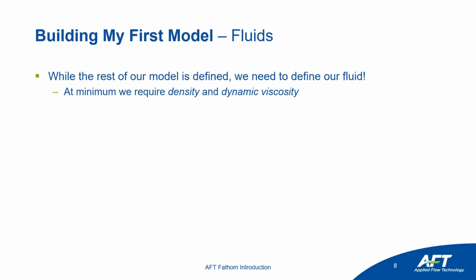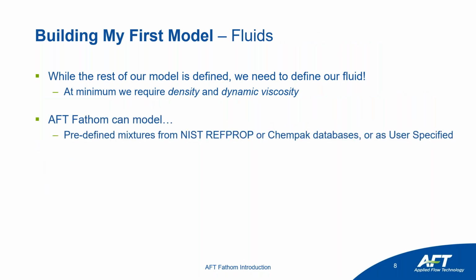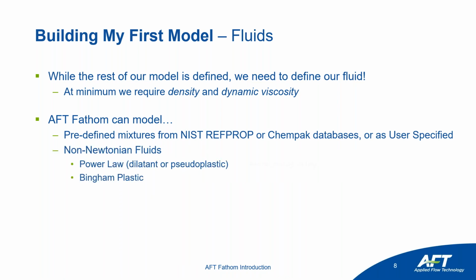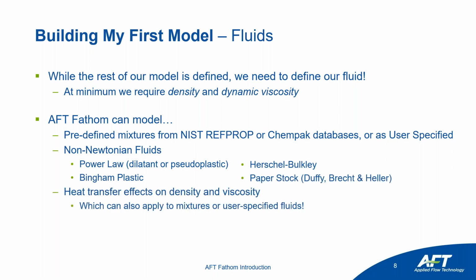We took a look at the different fluids. Again, for a custom fluid, we only require density and dynamic viscosity, but we can also model those predefined mixtures using either the built-in NIST RefProp database or the optional ChemPack database. We saw the range of non-Newtonian fluids that we can model. We'll also be able to capture those heat transfer effects, which can impact density and viscosity, which you can also apply to mixtures or user-specified fluids, depending on the information you're providing the software.